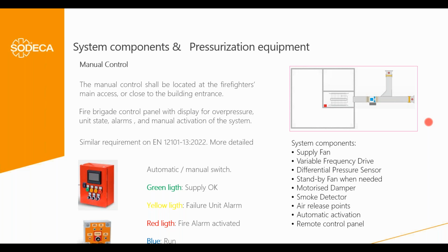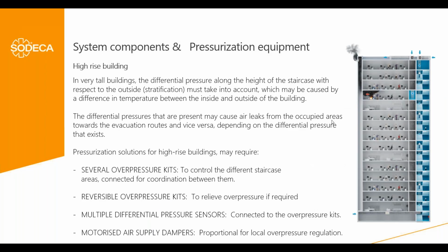And here, through this touchable screen, you can also make the self-commissioning with the Kitbox PDS Smart. It's like an iPhone, let's say. When you start, you say, okay, I have one air intake, or I have 2 through flaps or through motorized dampers. I have pressurization of the staircase, or the lobbies, etc. You follow all the steps, and it's very easy to commission the system.